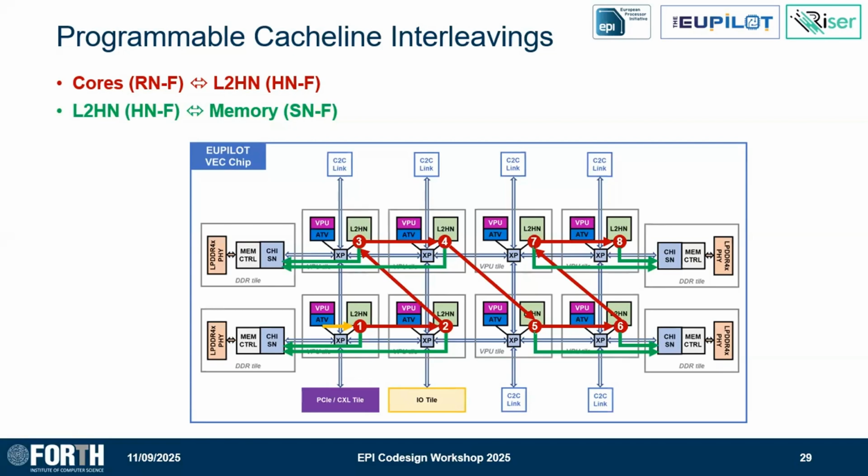That could be starting from 10% if the NOC is very, very big. So doing uniform random accesses across a NOC, even at 10% injection rate, the network gets saturated if it's like 8 by 8.